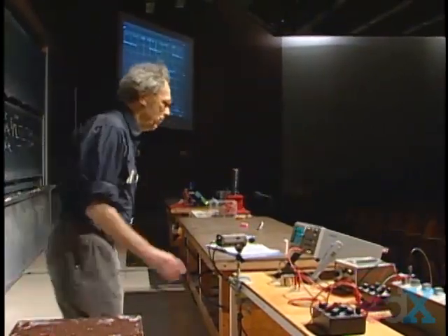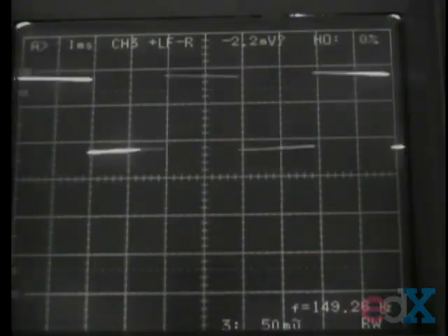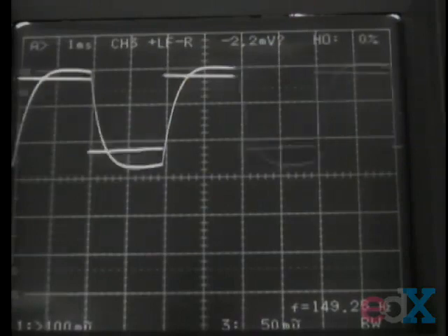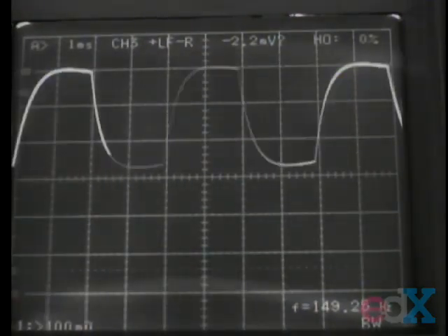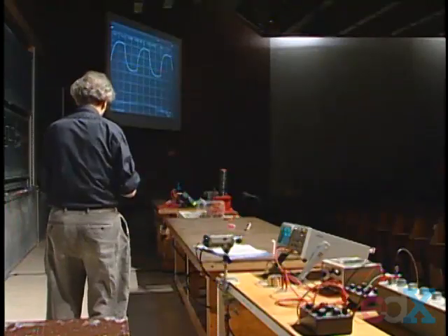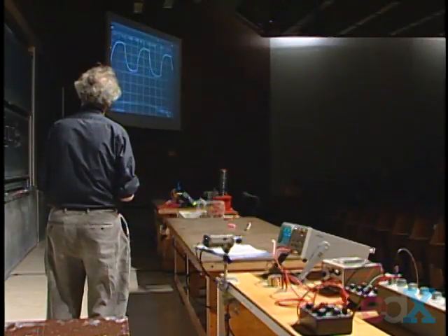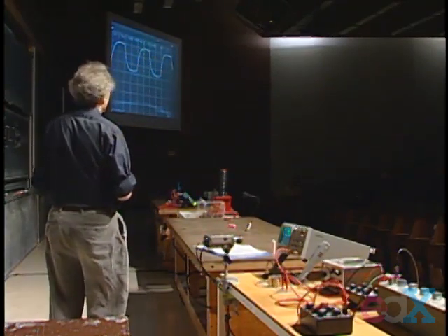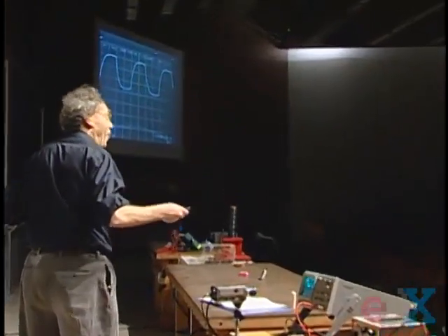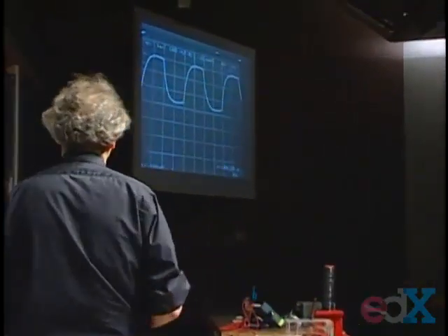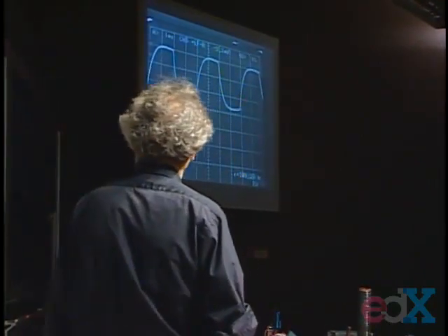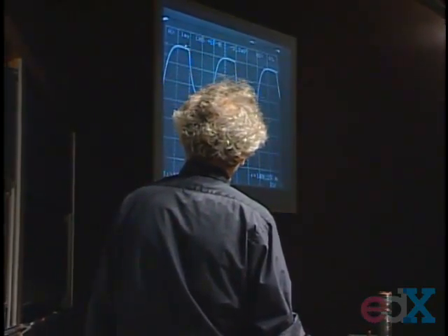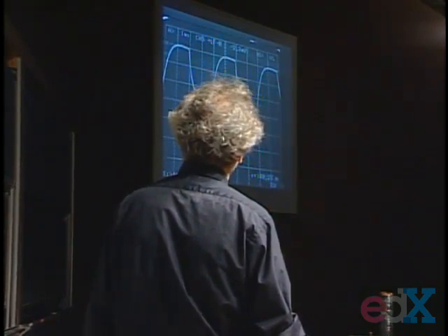And now I'm going to show you the voltage over the capacitor, and I will take the other one out. And here you see indeed exactly the image that we discussed. So you see early on the charging of the capacitor, and it reaches effectively the maximum value. You don't have to wait infinitely long. We say infinitely long, but clearly if you wait 3 or 4, 5 times RC, then you're almost there. And then here, I'm going to switch it back to position 2, and you see it's discharging.